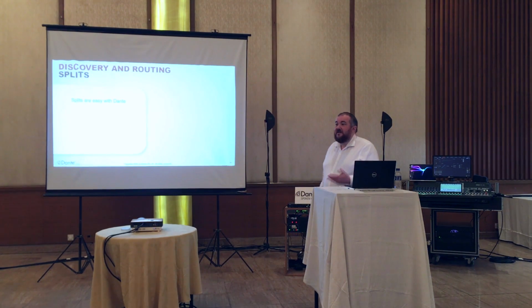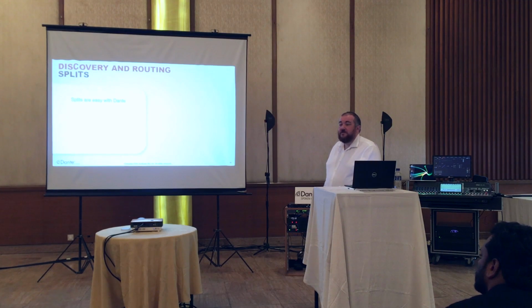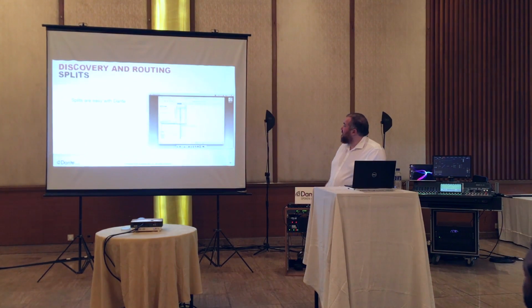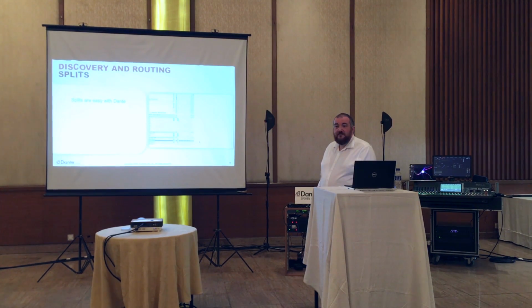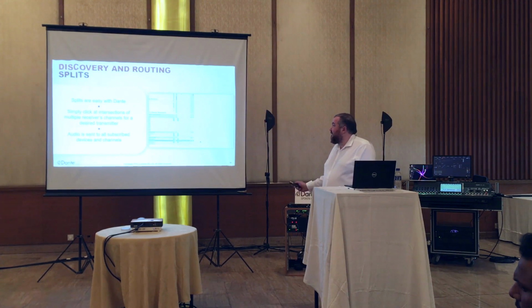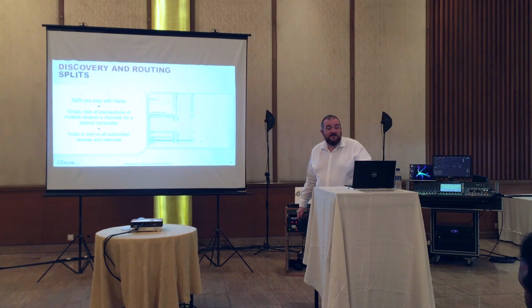You can also do splits. So I can take a single source and split it to multiple destinations. Very, very easily done. I can just decide which channels I want to split. So this channel 1, I can send to multiple inputs of the same or different devices. And there you see we're just having good audio subscriptions, just like that. And it's just simply a case of routing away like normal. And audio will be sent to all of the subscribed devices and channels in this case.